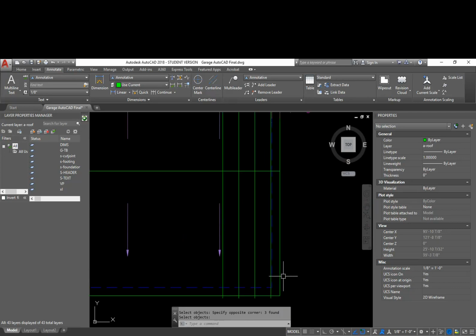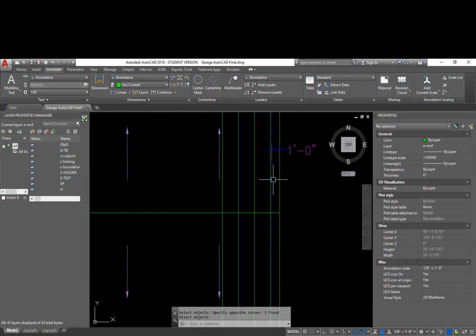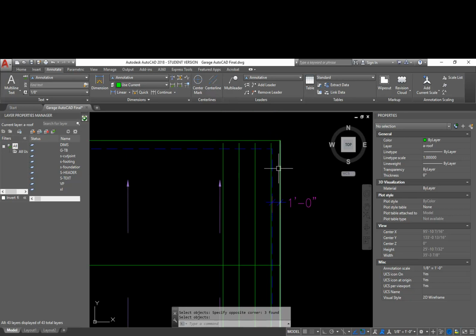So you can put 1 foot block of wood out here on the end of this truss in several locations, and then a 2x. If you're using a 2x4 fascia, then I use a 2x4 to create that rake. If I'm using 2x6, then I'd use a 2x6.